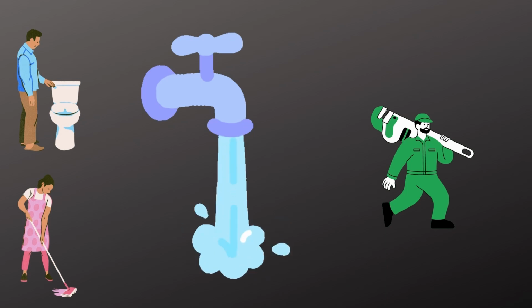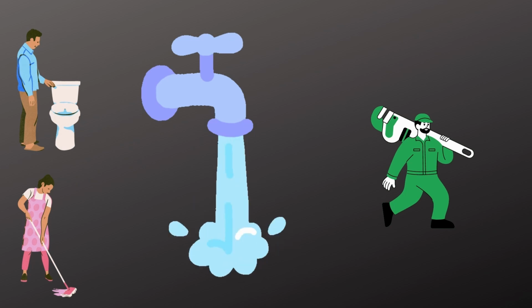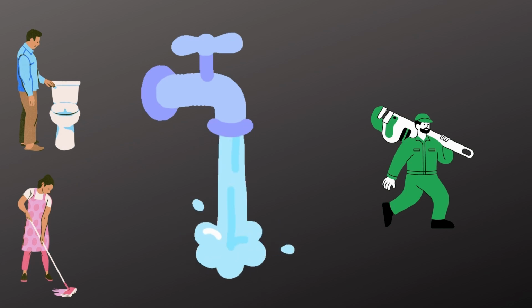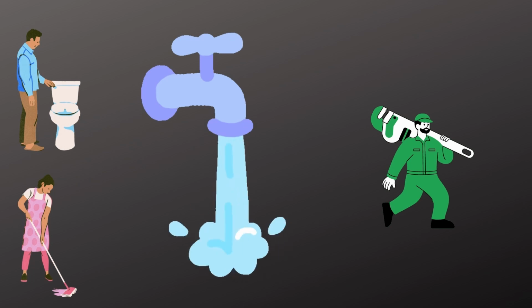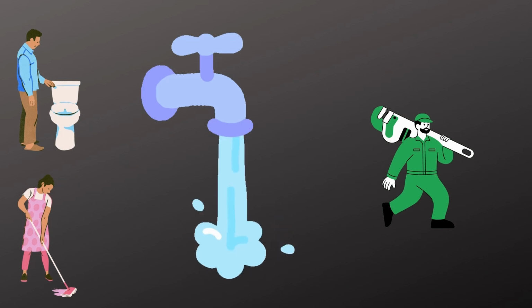Septic tank design is done by a separate professional company. In Ontario, Building Code Part 8 deals with septic design, construction, operation and maintenance. For the septic permit, you have to provide drawings with the building drawings and documents to the city.